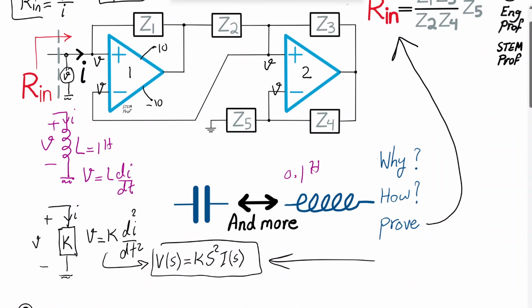So then let's start. We have voltage V across Z5 and ground, so there is a plus minus V across Z5. Therefore, I can easily compute this current, which can't go through the input of the op-amp because it has zero current due to the infinite input impedance. And therefore, there is a current I that flows this way and continues toward ground.